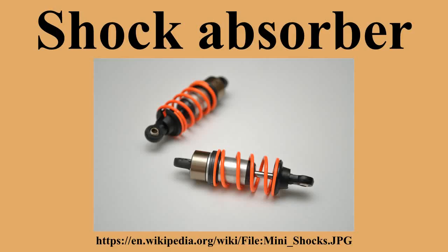The first production hydraulic dampers to act on the main leaf spring movement were probably those based on an original concept by Morris Houdaille, patented in 1908 and 1909. These used a lever arm which moved hydraulically damped vanes inside the unit. The main advantage over the friction disc dampers was that it would resist sudden movement but allow slow movement, whereas the rotary friction dampers tended to stick and then offer the same resistance regardless of speed of movement.